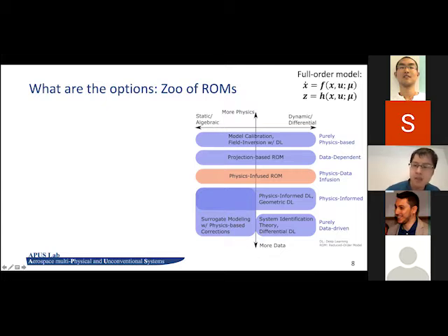Now here I'm adding one more axis. If we think in terms of a static problem, like aero-structural optimization, then most of those are static. The structure only deforms due to the aerodynamic force, but it doesn't vibrate according to that. On the other hand, we have the more dynamic ones, where the structure actually vibrates, so the motion is governed by a differential equation. This, for example, is a limit cycle oscillation kind of analysis.